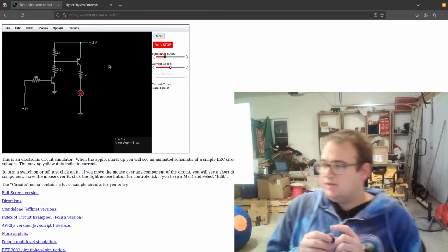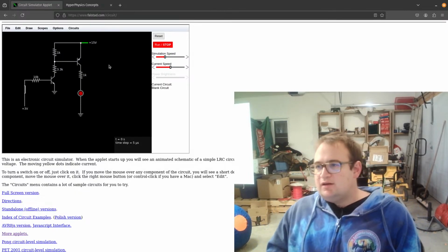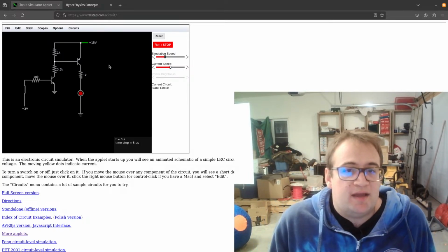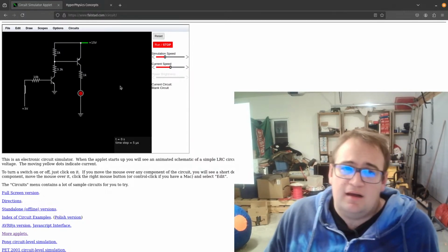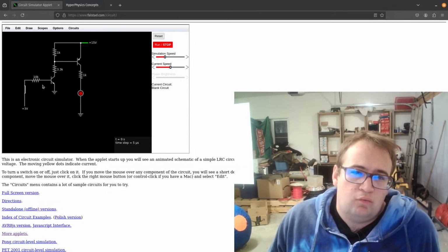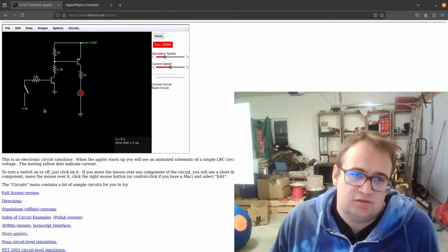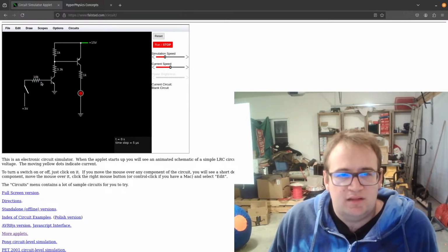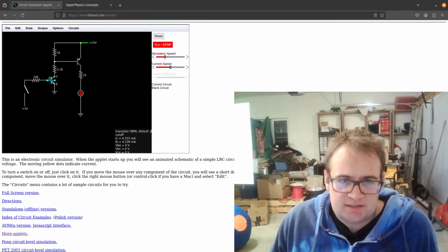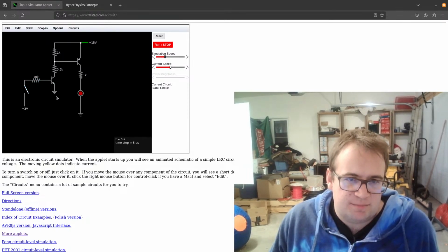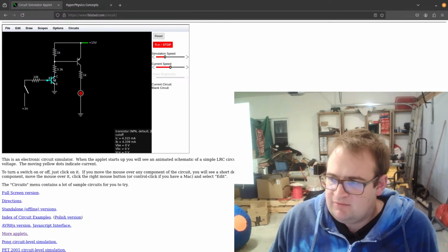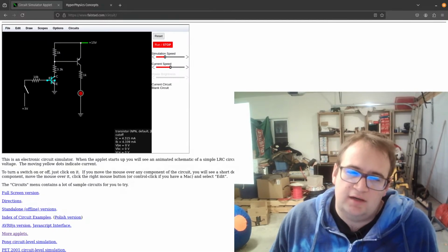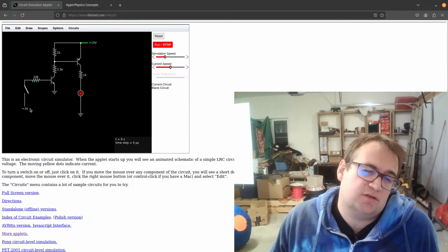Okay. So basically, if you think of currents, which it's usually best to do when you are dealing with transistors, when I close this switch and apply this 3 volts to this transistor, then there will be current flowing into its base, which, given that it has a beta of roughly 100, it will draw. So we have 3 volts. 3 divided by 10 is 0.3.